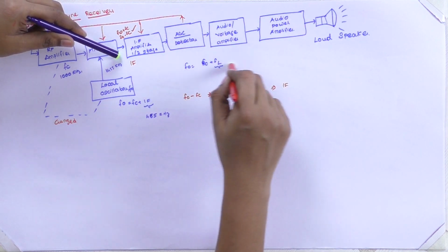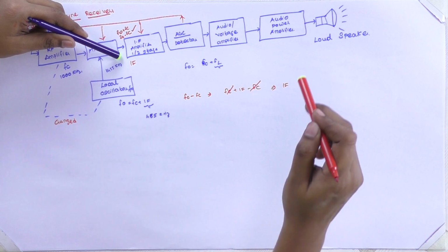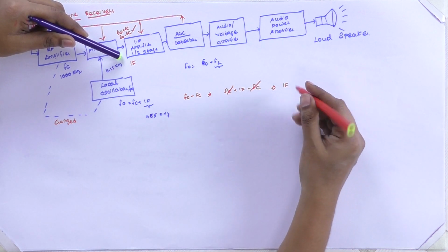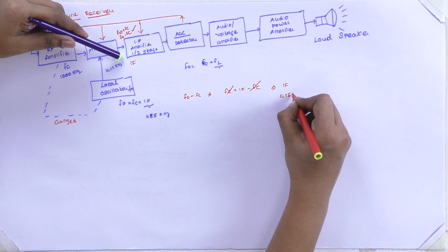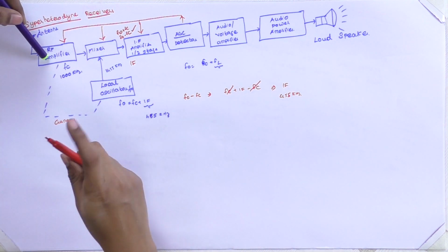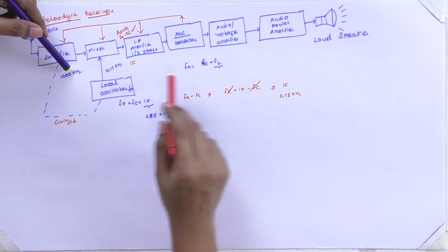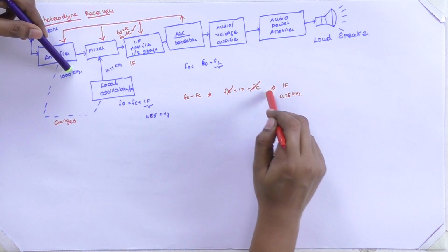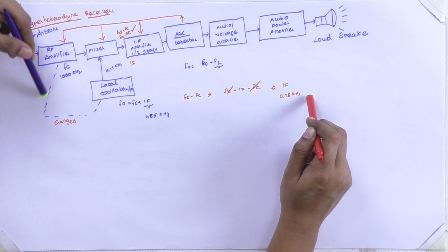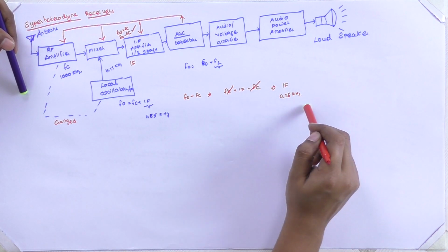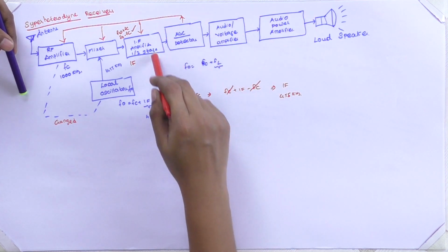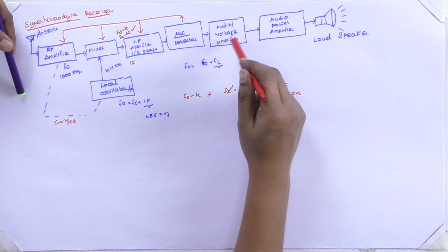Therefore, these amplification stages will handle only the intermediate frequency of 455 kilohertz, instead of the high frequency we received, such as 1000 kilohertz. We reduce our frequency from whatever the incoming frequency may be to 455 kilohertz in order to maintain stability in our receiver section.